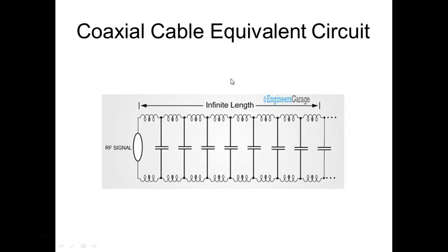And when you do that, it sets up this characteristic impedance, and it's got an infinite length. So if it's rated at 100 megahertz or something, that's when the characteristic impedance comes into play. You cannot measure the characteristic impedance of a cable with an ohm meter.